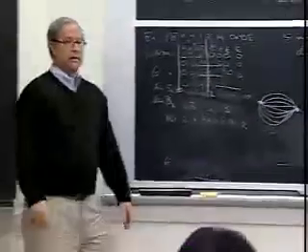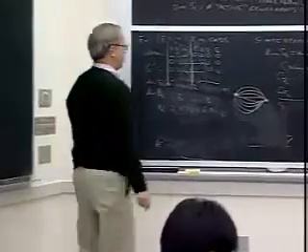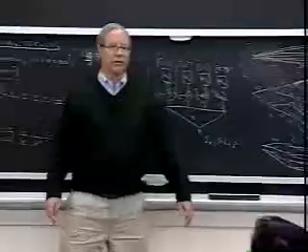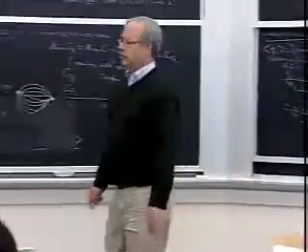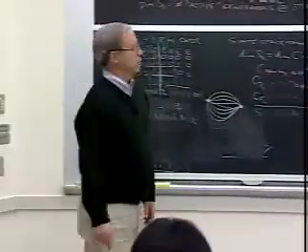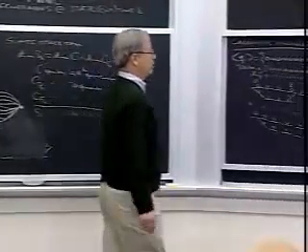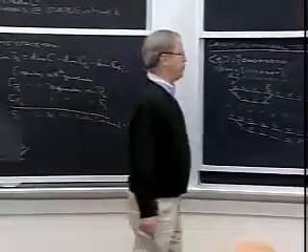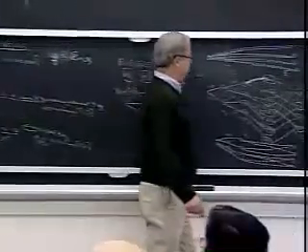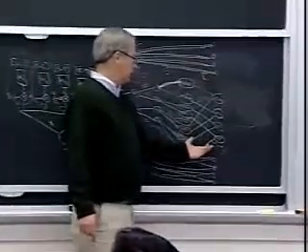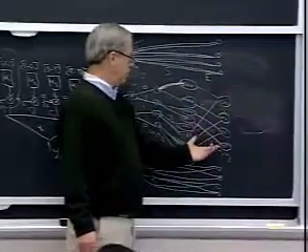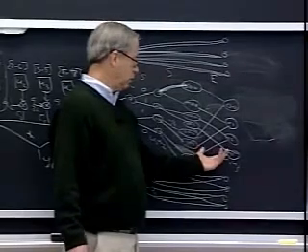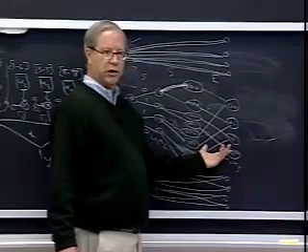Okay, it's easy. And it's not very productive. It doesn't really change the complexity of the Viterbi algorithm or the representation of the code. So these are just a couple of arguments to say, really, the branch complexity is more fundamental. We want to focus on branch complexity a little bit more. But of course, if you have a fully displayed trellis, the maximum state space dimension is either going to be equal to the maximum branch space dimension or 1 less than it.